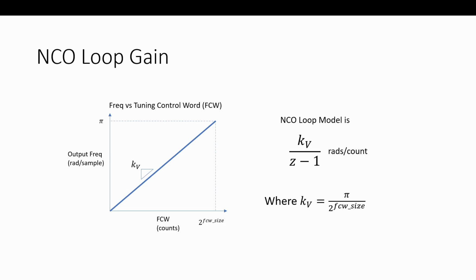So the pi is representing normalized frequency. If you divide the frequency axis on your digital by the sampling rate, then your digital frequencies are going from 0 to 1, Fs being the sampling rate. If I divide by the sampling rate, Fs over Fs is 1. So you'll see frequency axes in a digital domain going from 0 to 0.5, representing DC to the Nyquist, half the sampling.